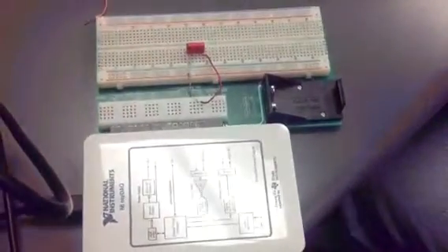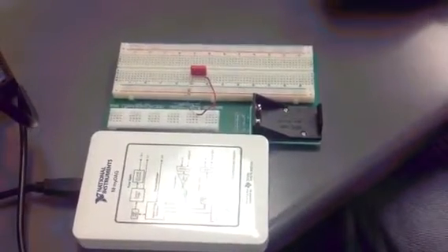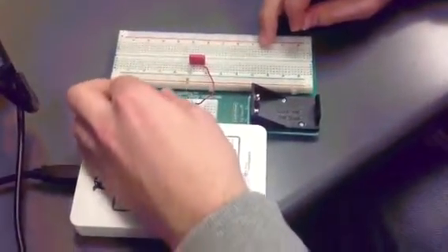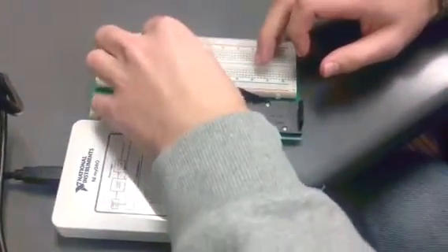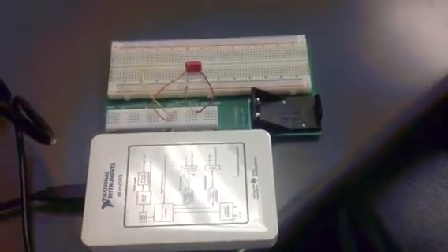And that's that. For part A of this experiment, we want you to measure the voltage across the resistor. So what you want to do there is connect AI plus into the plus side of the resistor, and AI minus connected to this side here. Struggling a little bit here. There you go.